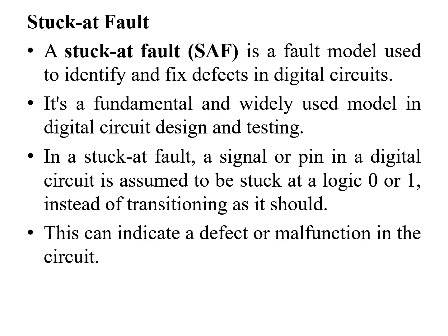Stuck-at fault. A stuck-at fault is a fault model used to identify and fix defects in digital circuits. It is the most common fault model. It is a fundamental and widely used one in digital circuit design and testing. In a stuck-at fault, a signal or a pin in a digital circuit is assumed to be stuck at either logic 0 or logic 1 instead of transitioning as it has to do. This can indicate a defect or malfunction in the circuit.